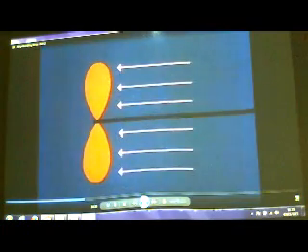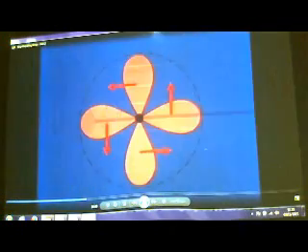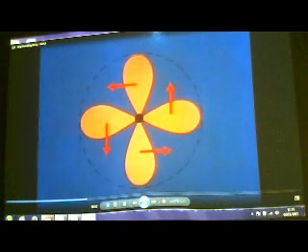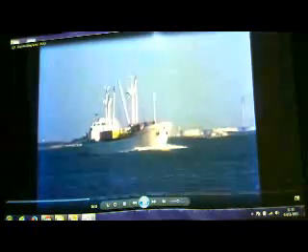As long as the water entering the propeller disc has the same velocity over the whole area, and its path is parallel to the propeller shaft, the lift and drag generated by each blade are equal. Under these conditions, there will be no net transverse force caused by a deeply immersed propeller. Unfortunately, when a ship is running ahead, this is not the case.